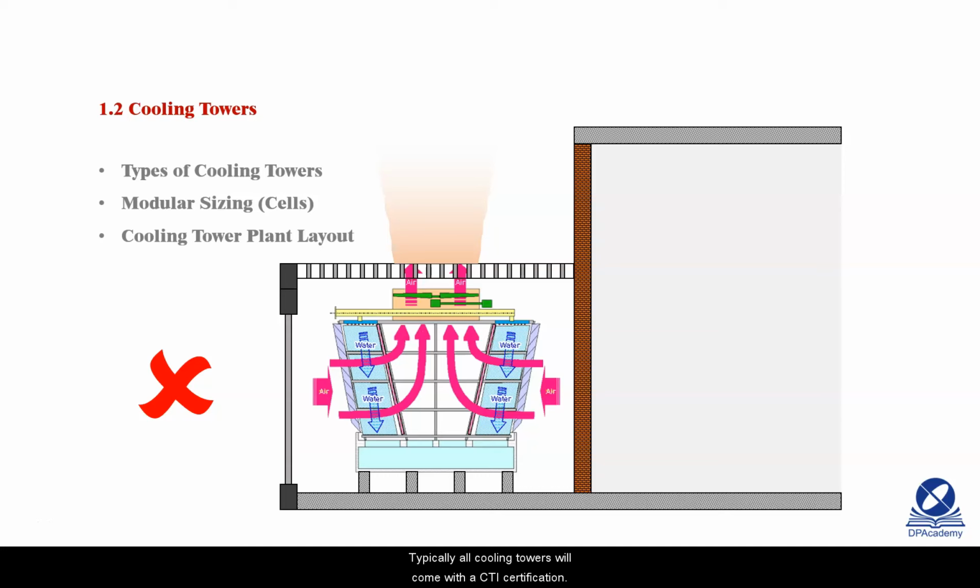In Singapore, the URA requires that a trellis goes over the top of rooftop plants. However, this affects the performance of the cooling towers, and URA will allow for openings above cooling tower fans. It is not simply the performance of the cooling tower that we should be worried about, but also to ensure that the manufacturer's warranty is not compromised.